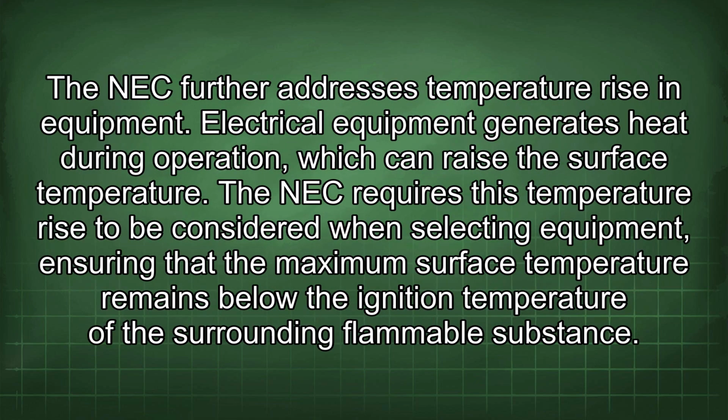The NEC further addresses temperature rise in equipment. Electrical equipment generates heat during operation, which can raise the surface temperature. The NEC requires this temperature rise to be considered when selecting equipment, ensuring that the maximum surface temperature remains below the ignition temperature of the surrounding flammable substance.